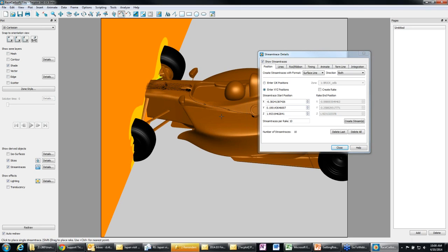Multiple edges. Okay. So Mohammed, maybe that's a question that we can bring in STL files. He had asked a question about whether or not you can bring in, he's trying to create zones for complex geometry. Right. We can bring in STL files, so you would be able to bring in CAD data in that format.